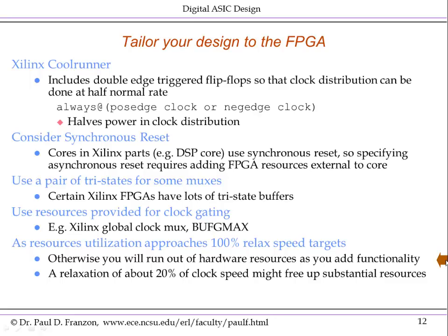Thus, one trick you can always leave to the end of the design cycle. Let's say you've got a function, you're trying to fit it within one FPGA, and it doesn't quite fit. Well, what you'll often find is that if you relax the clock cycle time somewhat, because high-speed operation requires parallel logic implementation, you'll actually free up logic resources and thus are more likely to fit your design within a specific FPGA chip by relaxing the clock a little bit.